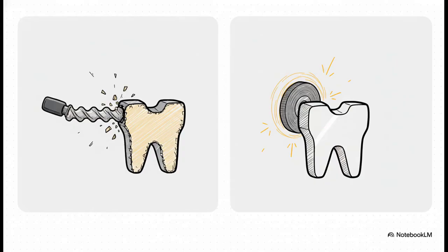So choosing between a process like hobbing versus a more expensive finishing step like grinding, that's a classic engineering trade-off, right? It's a balance between cost and precision. But for those really high-speed or low-noise applications, that extra grinding step is what buys you the accuracy you need to prevent the dynamic loads that cause all that noise and vibration in the first place.